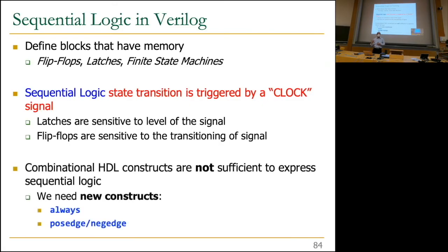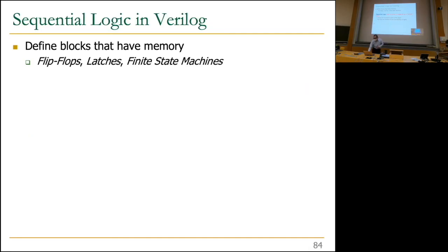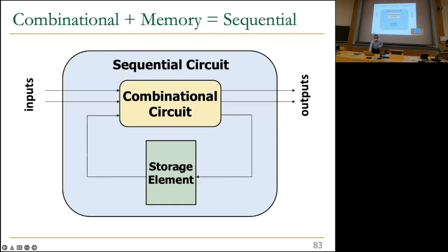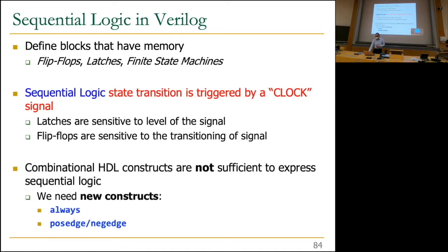And we described why this was necessary, right, for building finite state machines, because you need to have the entire clock cycle available for the state, because that state, that value, is used in the combinational circuit over here. So as you can see over here, the value of the state is used in the combinational circuit along with the inputs. And the combinational circuit design assumes that the clock cycle is long enough such that the function that you implement in the combinational circuit finishes within that time before the next state is captured in the storage element. Hopefully that makes sense. This is just a summary of, let's say, part of the last lecture. We're going to talk about the timing later on tomorrow.